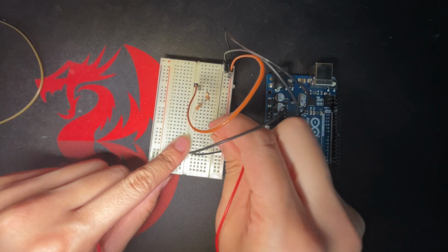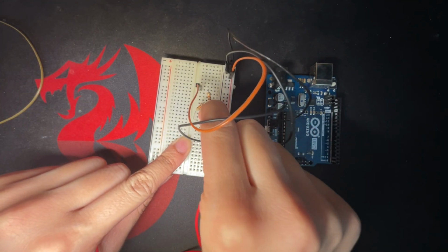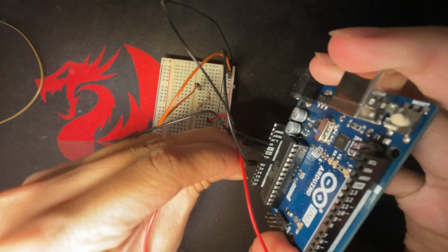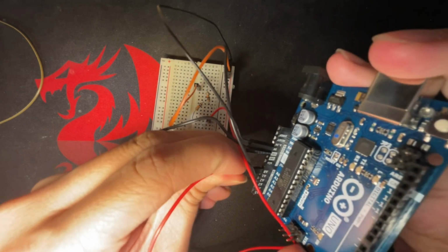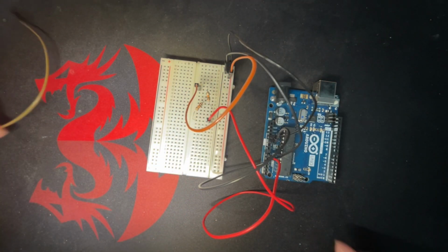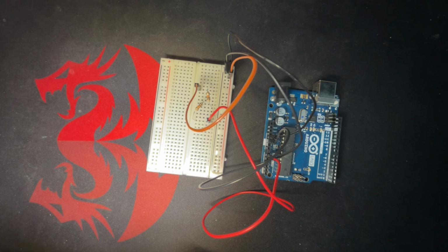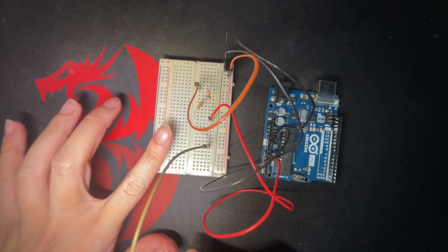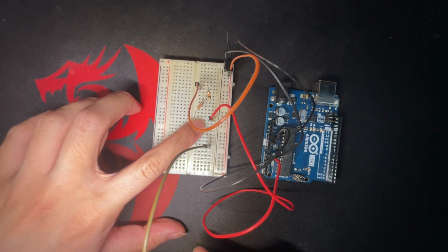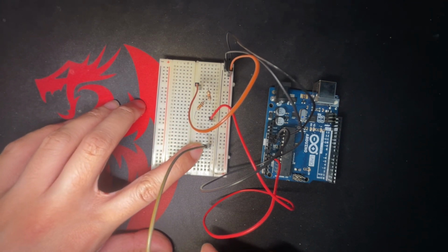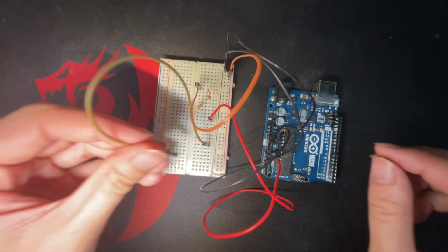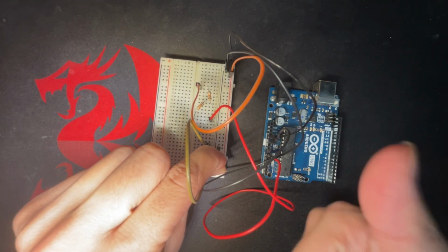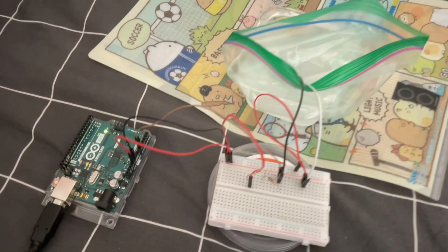Then along that same line as your resistor, gonna put another pin and plug that one into analog. This one is for the purpose of recording your voltages, and that comes up in the formula, and I'll show you guys that in my code. Then just taking something far out, and I know it's an incomplete circuit, but here and here are where the connections to the RTD would go. And then this pin would just go to the negative side to fully complete that circuit. There you have it. This is the final circuit.